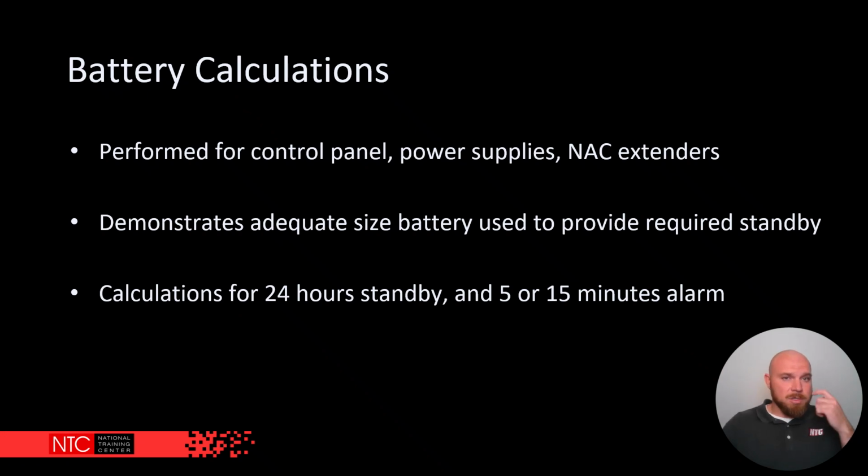Our battery calcs are there to ensure that that system has the adequate capacity for its secondary power. They'll be performed on your control panels, power supplies, NAC extenders. If you have voice evac, that has its own qualifications, its own requirements that need to be made. Demonstrates that we have the adequate size battery provided for the required amount of standby that we need.